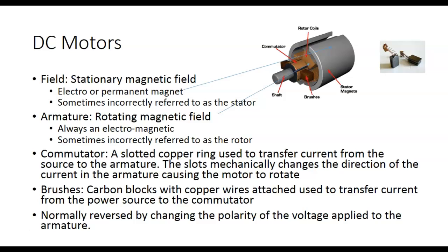It won't, because you've got to swap the relationship between the fields, right? That's also true enough. We normally change the polarity on the armature. That is the industry standard. I've never seen one changed with the field, but I'm not going to say you won't run into that, because we run into problems with screwing around with the field on some of our motors.